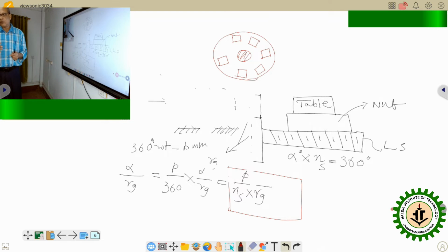In case of open loop control system, it was through the stepper motor, but in this case it is expressed in terms of the precision movement that the system can capture by the feedback device. Whatever may be the displacement, it is possible to capture only by the feedback device, and this encoder disc is the feedback device.